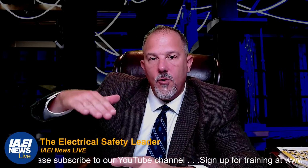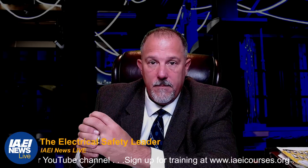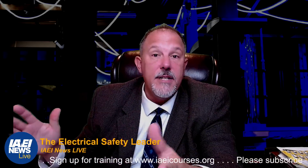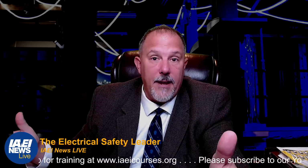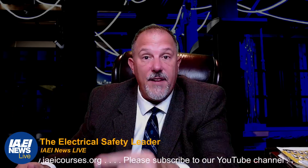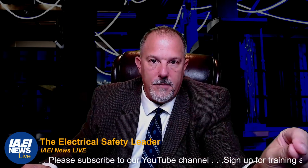When you start with the current, remember, we're starting with the current of the load, continuous current. Let's say it's 100 amps of continuous current. 1.25 times 100 is 125 amps of continuous current. Then you pick your conductor.